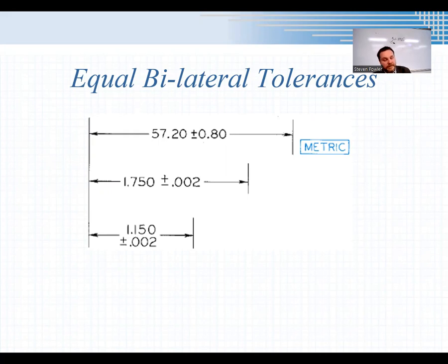If I'm manufacturing something made out of plastic, changes in the humidity in the air will change the temperature at which that plastic melts and the viscosity of it as it flows into a mold or something like that. Just something as simple as the humidity in the air. And here in our state, we know that's going to vary from hour to hour. That would be enough to alter the size of something as I'm manufacturing it. So unless I've got a really expensive facility where I'm controlling the temperature and humidity inside a large facility, which is very rarely reasonable, I'm going to experience some variation as I manufacture something.